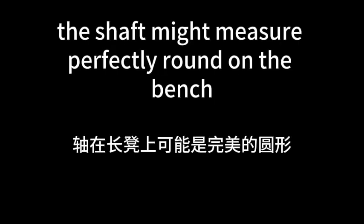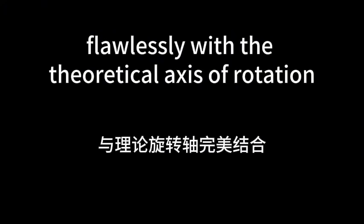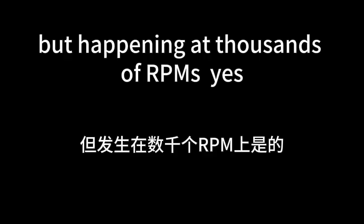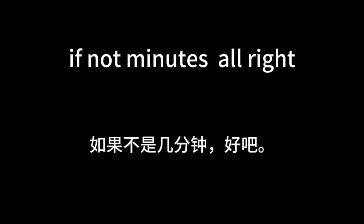It's eccentricity. The shaft might measure perfectly round on the bench, but if its center of mass doesn't align flawlessly with the theoretical axis of rotation, you get radial runout. So it's essentially the engineering term for a wobbly shopping cart wheel, but happening at thousands of RPMs. Yes. And at those speeds, that periodic vibration will shatter the surrounding bearings in hours, if not minutes.